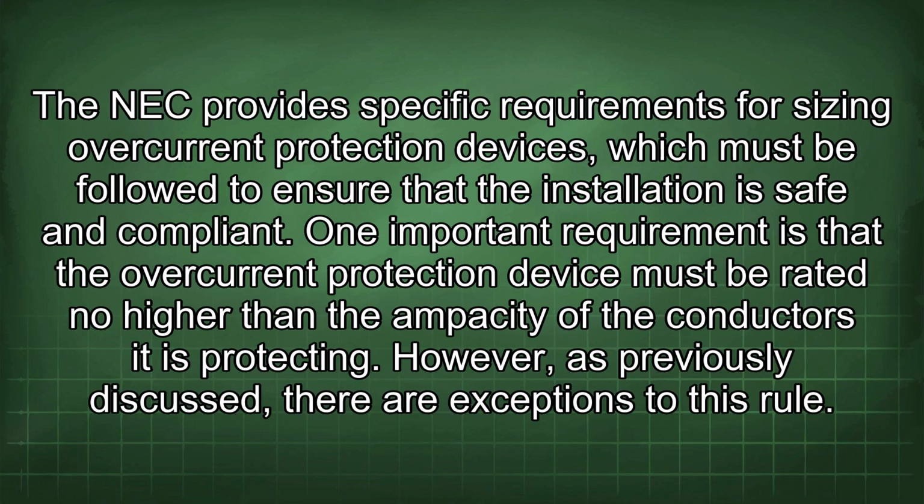The NEC provides specific requirements for sizing overcurrent protection devices, which must be followed to ensure that the installation is safe and compliant. One important requirement is that the overcurrent protection device must be rated no higher than the ampacity of the conductors it is protecting. However, as previously discussed, there are exceptions to this rule.